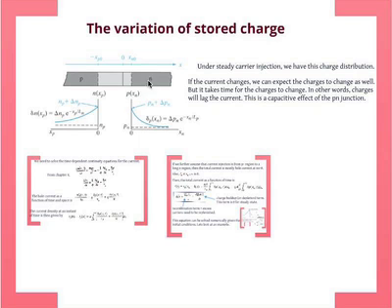Now, of course, with the electrons, the same thing happens. The majority carriers here get injected across the junction, and then they diffuse. They create a steady state distribution which looks like that. Because you have a concentration gradient, the electrons are diffusing from right to left. As they diffuse, they also recombine with holes, because there are lots of holes in p-type material. But at the same time, this recombination and diffusion is balanced by the carrier injection. So you have a steady state distribution. This is equilibrium.